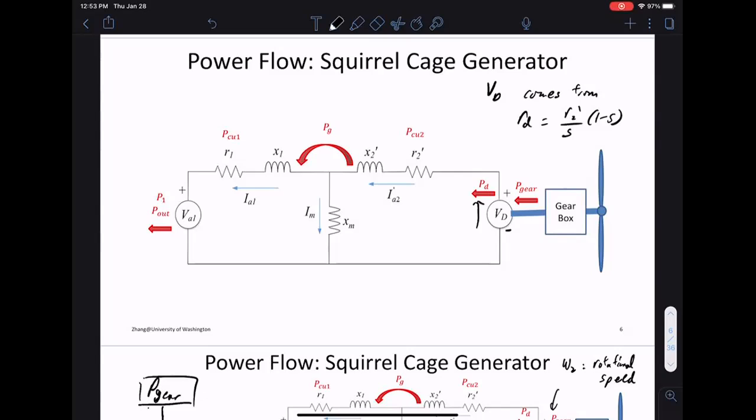Yeah, this is the important part actually to understand why they're in phase, so why there's no reactive power out of this, right? So again, if you look at the circuit diagram, just look at this part. So really what you have is this RD, right? And you're pulling current out this way. Okay, we're pulling current out this way. And we're asking what is the voltage across this resistor? This voltage is basically VD, right?